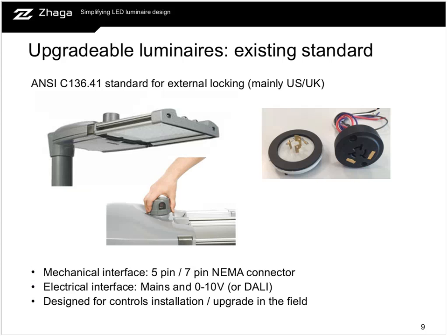The major item is that it is a mains compatible node, which has quite some implications for the connector. And typically it has either a 0 to 10 volt functionality or a DALI controls functionality. And as indicated, it is designed to install controls either from the beginning or upgrade in the field.